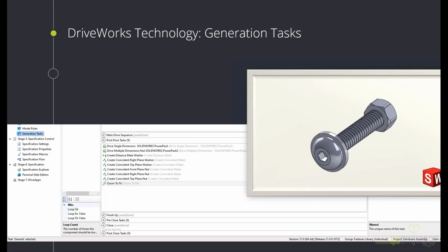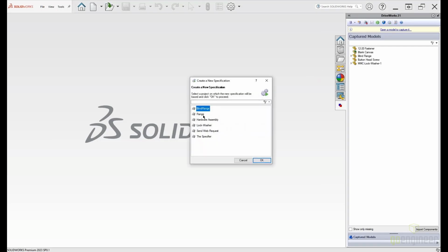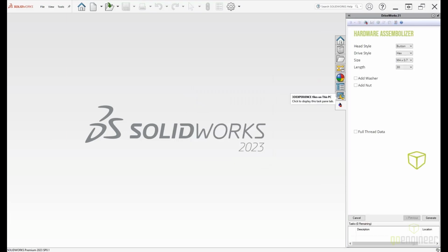So before we get a look at how everything works, let's take a look at how we would build an assembly. I can choose between different types here. You could have this look any sort of different ways. Here I'll select Torx, and you can choose between M4 or M5. And all of these are just different available lengths that are at my disposal based off of the table data itself. So this is actually going off of a similar table as the blind flange data.